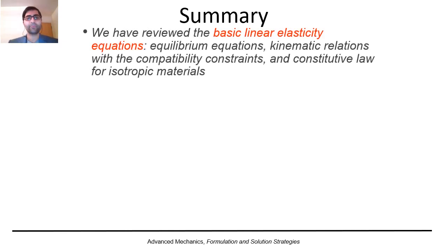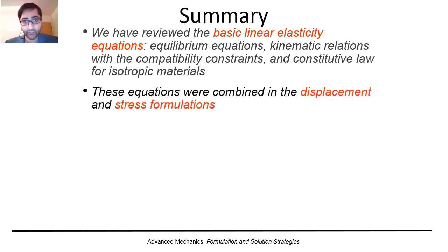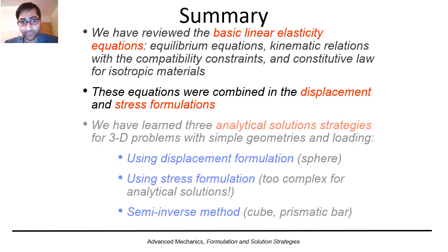In summary, we've reviewed the basic linear elasticity equations: equilibrium equations, kinematic relations with the compatibility constraints, and constitutive laws for isotropic material. These equations were combined in the displacement and stress formulations.